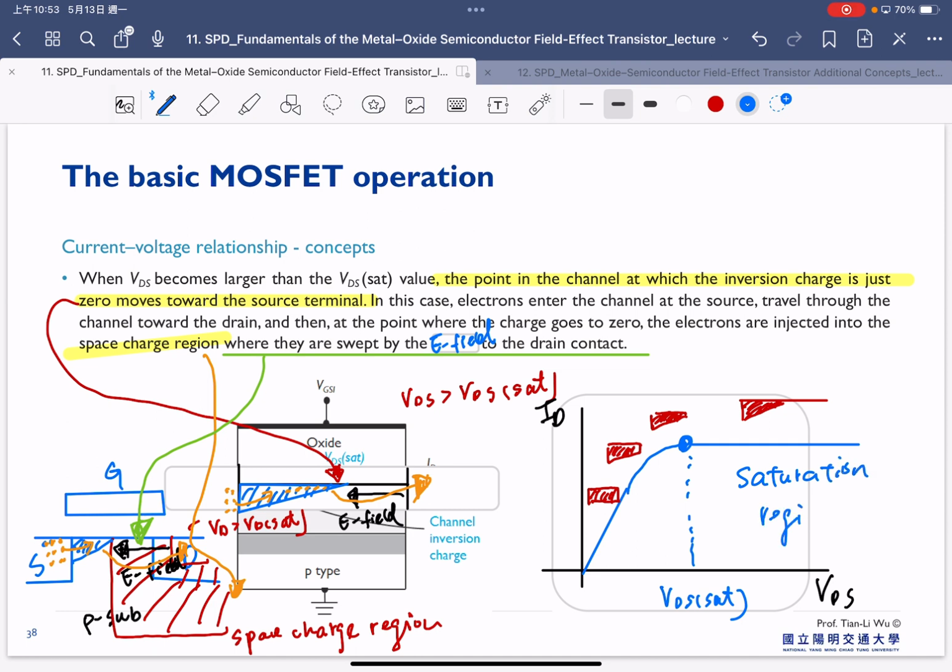This is because right now the current is saturated, and the region where we have the linear dependency on the gate voltage is the region we call the linear region. Okay, so finally we complete the picture for the ID-VD characteristic for one MOSFET. Right now it's still based on the physics point of view, so we don't have any very hardcore equation now, but we can already expect what the ID-VDS looks like. And in the next slide we'll start to consider how to derive the ID-VD characteristic.